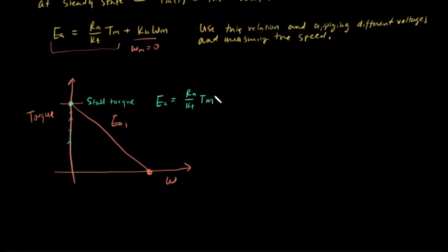When there's no load, here we have a zero load, and we can increase the speed, and we can get our max speed for this voltage. Then that's how we get our EMF constant, because in that case Tm is equal to 0, and this is called our no load speed. We can get an expression there that just says Kb is equal to the applied voltage over omega NL, and that's this point here.